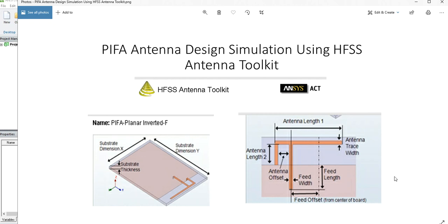Design a PIFA antenna. To design and simulate a PIFA antenna. As you know, PIFAs are commonly used in mobile phones because of their compact size, easy integration, and good specific absorption rate properties, because the available volume or space of the antenna is small compared to the wavelength. We'll be designing for a typical mobile layout, using an FR4 substrate.